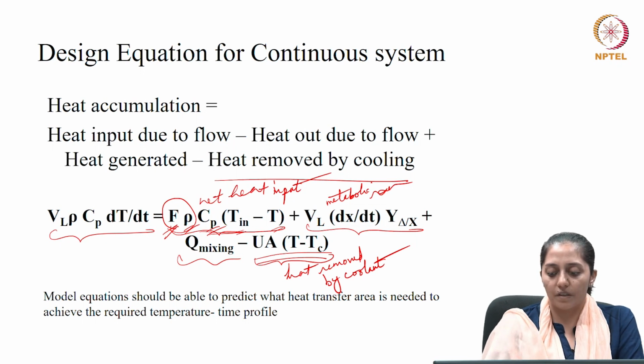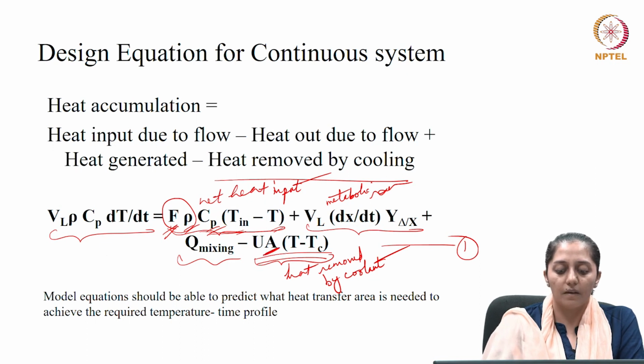Now, this equation given here can finally be used to predict the heat transfer area required to achieve the required temperature profile of the fermentation medium, given the coolant temperature.